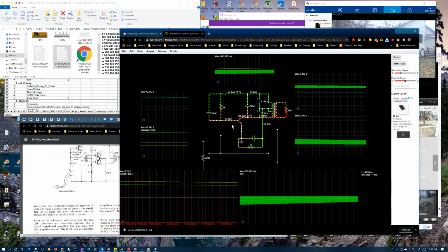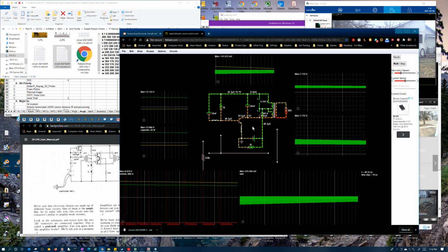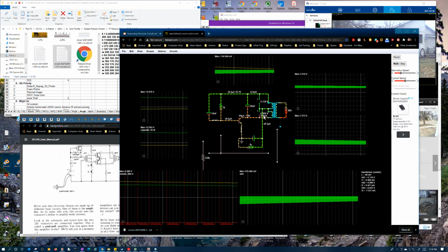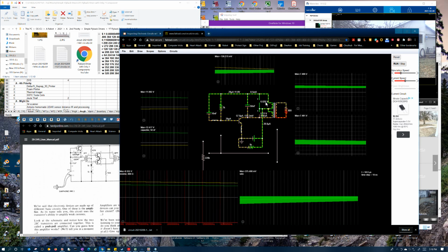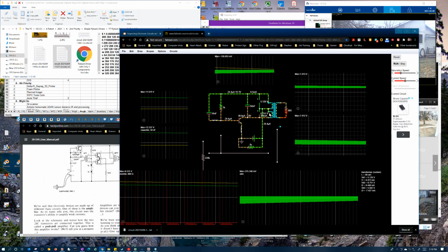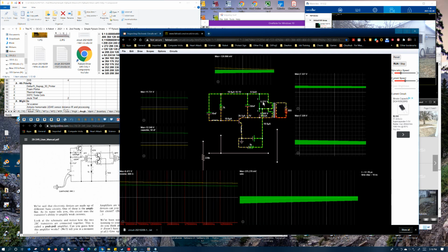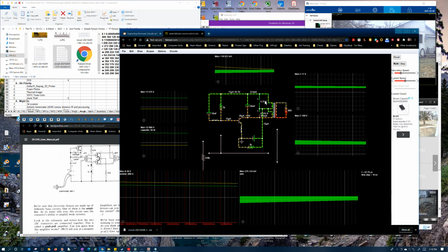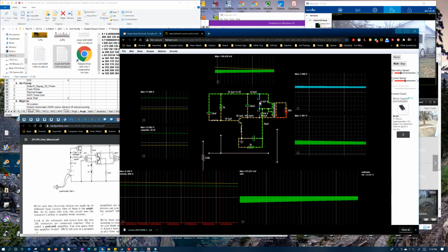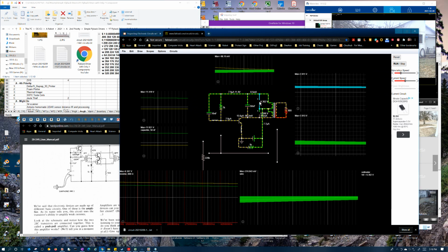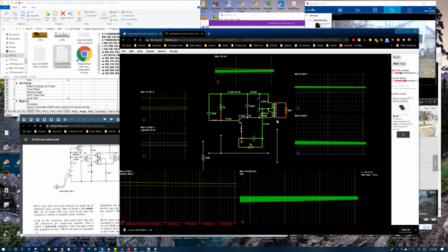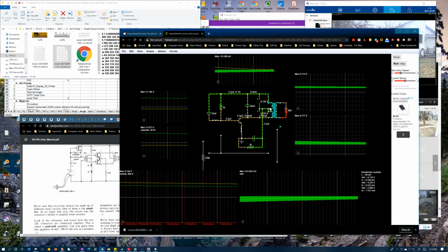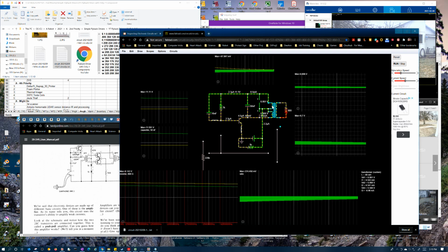But I just know this transistor is, that's why you see such low currents here, it's in a hard off condition while this field collapses, because it's still got a voltage on it. If this field had completely collapsed, this would be a negative voltage again. Theoretically, it should end up a negative voltage again at some point, just like it started with. Once the field is completely collapsed, there's nothing to provide an electromotive force on here.